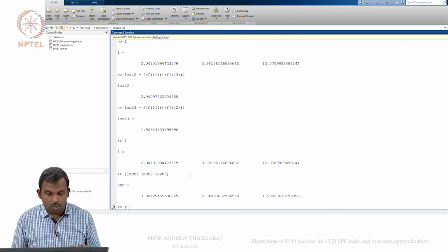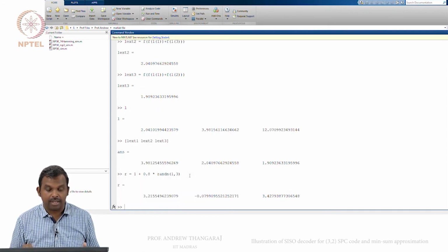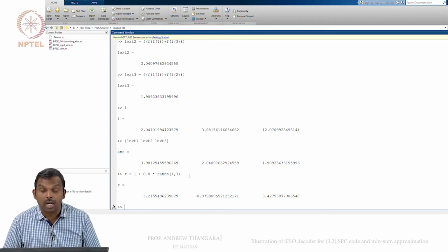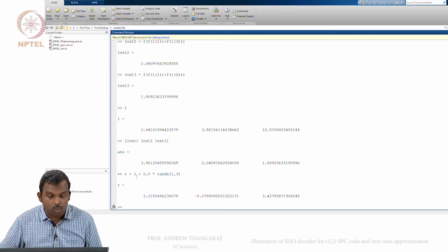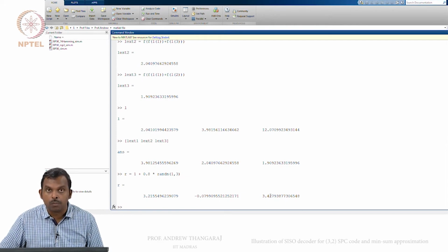Okay. So, let us try to do one more case where things maybe are a little bit more difficult. Okay, there it is. So, this is a received value where there was one error. Notice what has happened, I transmitted 111, three values 111. The first one had no error, the second one has an error, the third one has no error. Now what happens in the decoding is when you try and decode the second bit, you will go wrong, right, because it's already gone negative. So, if you just do a threshold decoding, you're going to decode that this is -1, on the other hand this is actually +1. Okay.